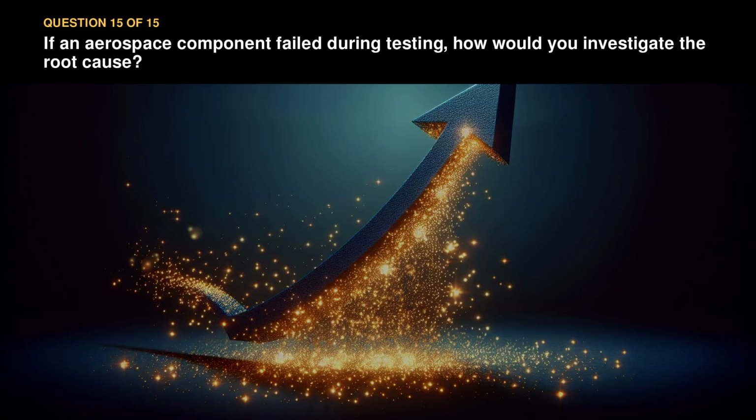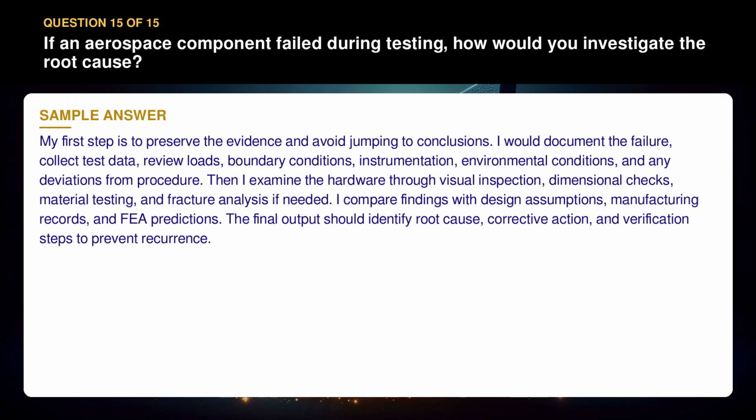If an aerospace component failed during testing, how would you investigate the root cause? My first step is to preserve the evidence and avoid jumping to conclusions. I would document the failure, collect test data, review loads, boundary conditions, instrumentation, environmental conditions, and any deviations from procedure. Then I examine the hardware through visual inspection, dimensional checks, material testing, and fracture analysis if needed.